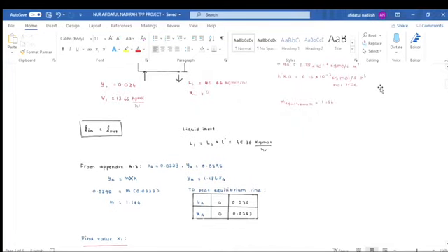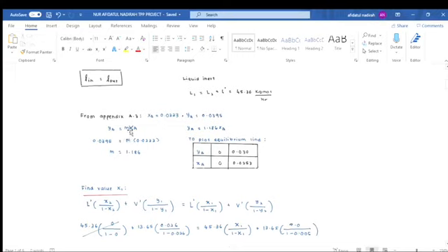So next, the question has already given us the value of the gradient for the equilibrium line, which is 1.186. We have to use it to develop the relation for the equilibrium line, which is YA equals m XA. It's stated here that XA is equal to 0.0333 and YA is equal to 0.0395. This value we can get from Appendix A.3 for acetone. After we substitute this value, we get the relation YA is equal to 1.186 XA.